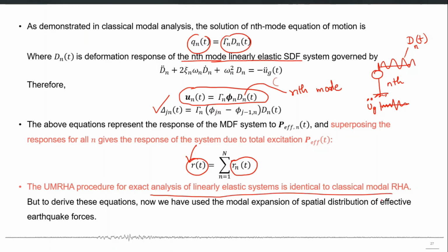But now let's use the same idea of the modal expansion of spatial distribution of effective earthquake forces and apply it to nonlinear systems. When you apply it to nonlinear systems, it is called UMRHA, Uncoupled Modal Response History Analysis.